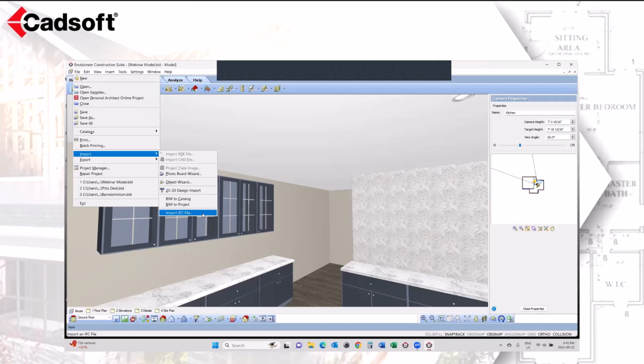We've updated our IFC background information so it recognizes more IFCs. Now, when you're bringing in an IFC, it is only as intelligent as the IFC that was created. So if they didn't put a lot of effort into their IFC file, we're only going to bring in the effort that they did. But if they put a lot of work into their IFC and separated windows from doors, from trim and everything along that line, we're going to recognize that too. And you can grab a complete model and have it in Envisioneer format very quickly and very efficiently.